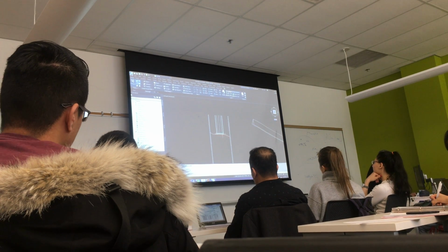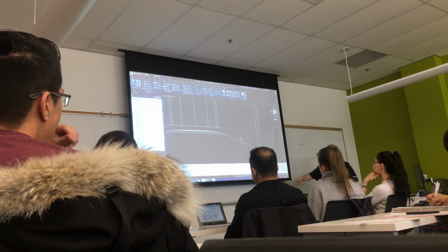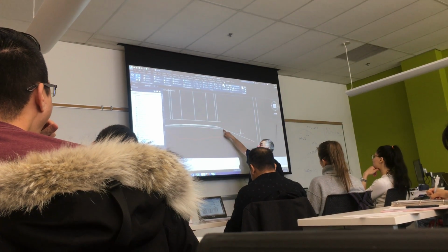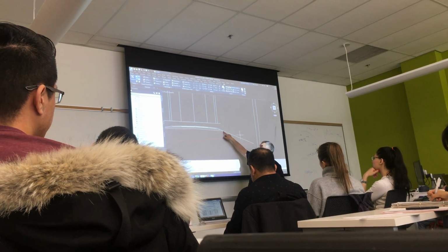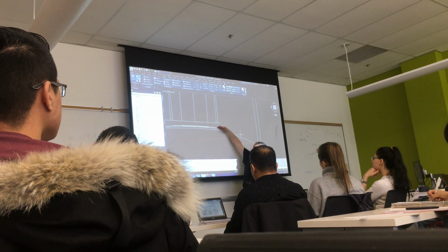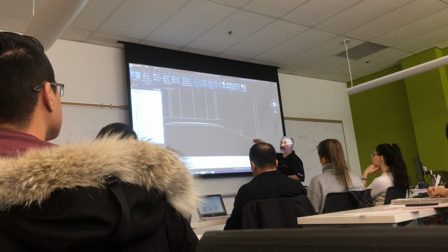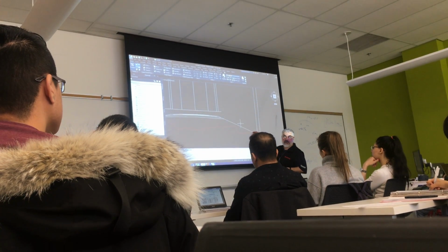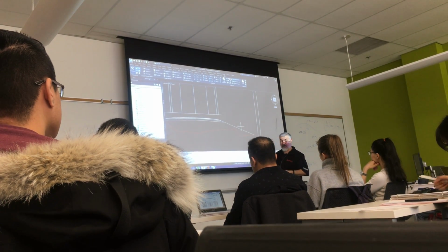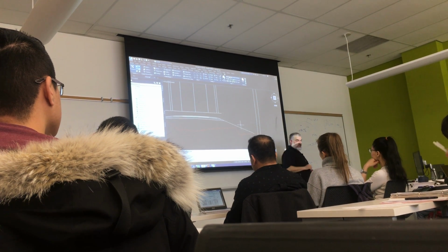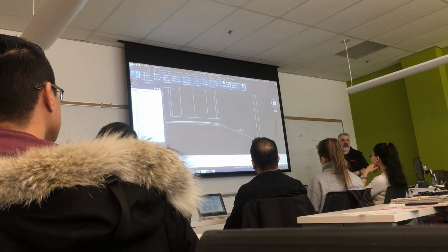That point where the subgrade meets the slope is the one that's key. If that's above the original ground, then you take that slope and you touch the ground and you're done. That's a fill slope. So those are the options, cut or fill. You can almost guess. For homework, you're going to have one of each as well. I want you to practice more.